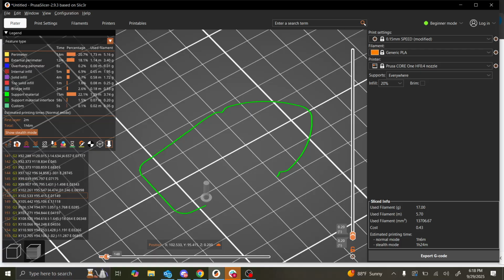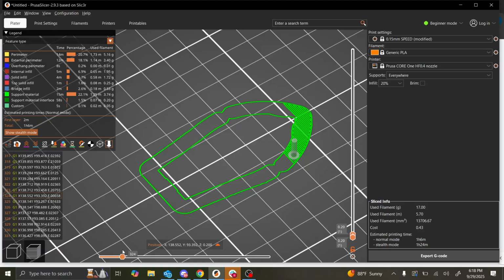So this little arrow drawing the line is every single command. Over here on the left is all the G code commands. A G1 command is a movement command. I'm just a nerd and I know how to read this, which is kind of sad. But basically, the 3D printer is kind of stupid and you need to tell it exactly what to do, right? Your computer is smart and it'll program the toolpath, and then your printer is just like, okay, I'll do it. It just listens to these codes and does it.